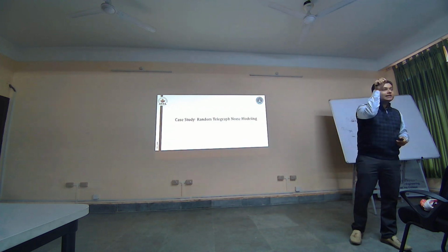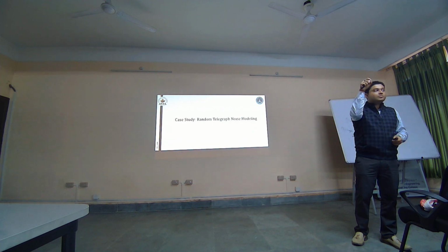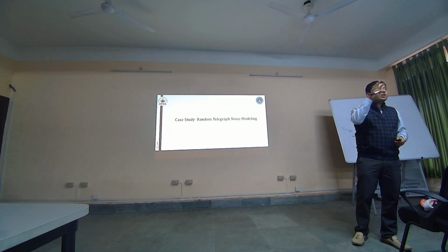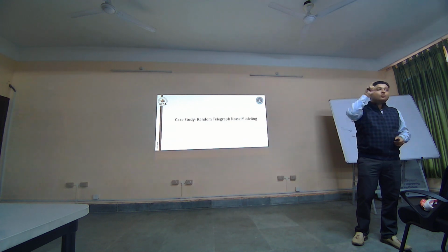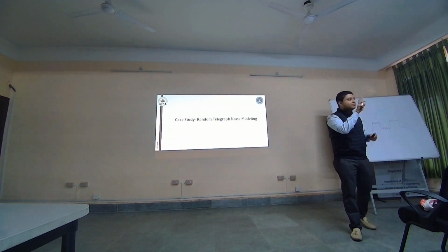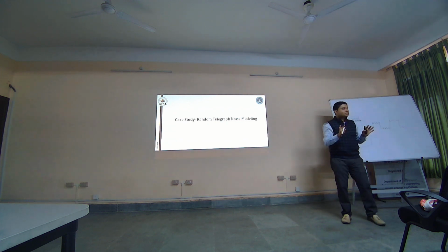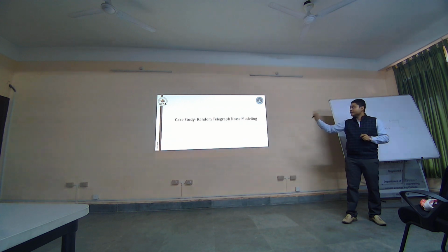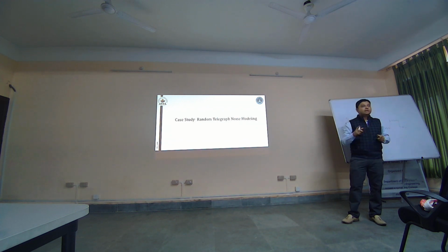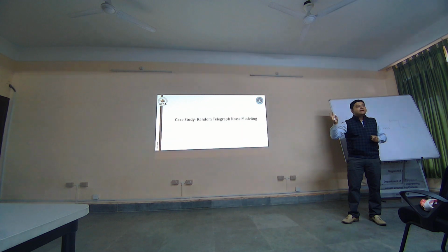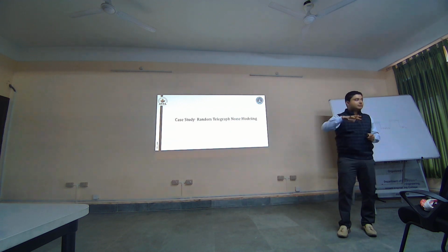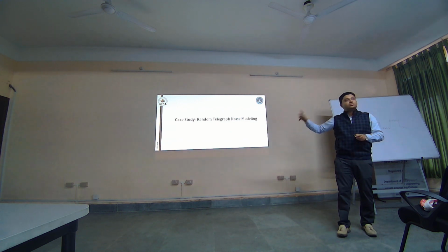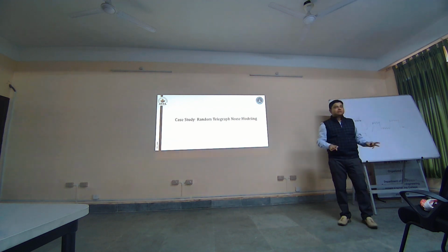Whenever you have a single trap in your device, it is said that you cannot have only one trap in your interface. There will be many traps, but at one point of time, only one may be dominant in different scenarios. That is where this random telegraph noise becomes very, very important. Therefore, random telegraph noise is defined with respect to the number of traps. If there is a single trap, you will have two states. If you have more than one trap, you will have more states. But our modeling is limited to only two states because that is the basic form of modeling.